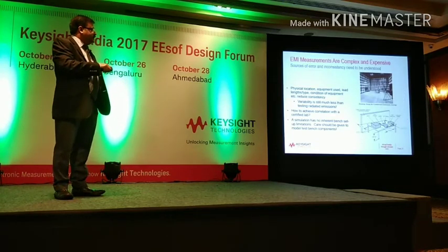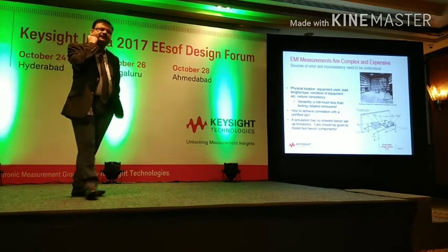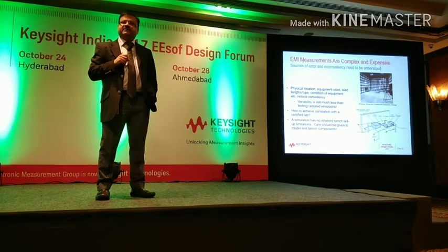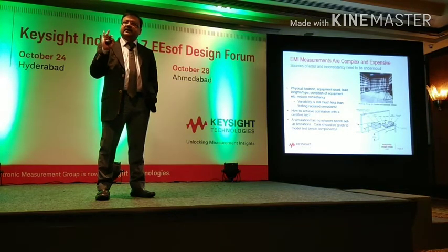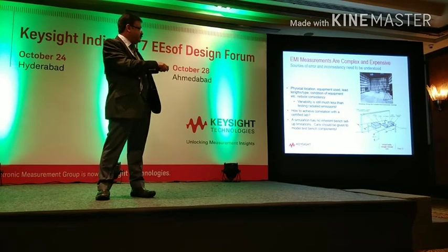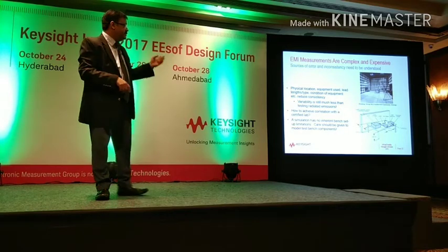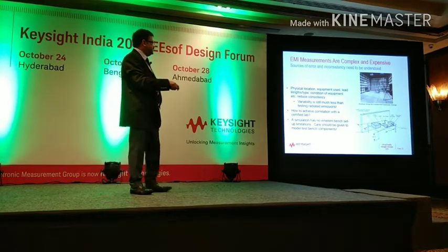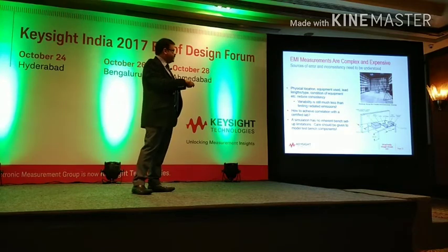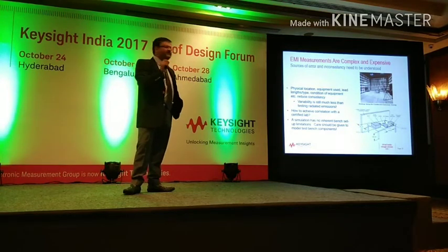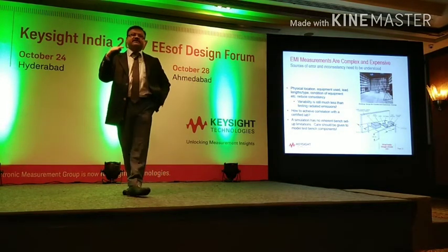Okay. So EMI, why would you like to do that? Because EMI measurements are expensive and complex. You need to set up a whole chamber, set up your electronics, do a conducted emission test and all that. You need to have these benches. And then physical location, equipment used, lead length, type of equipment, all that will reduce consistency.